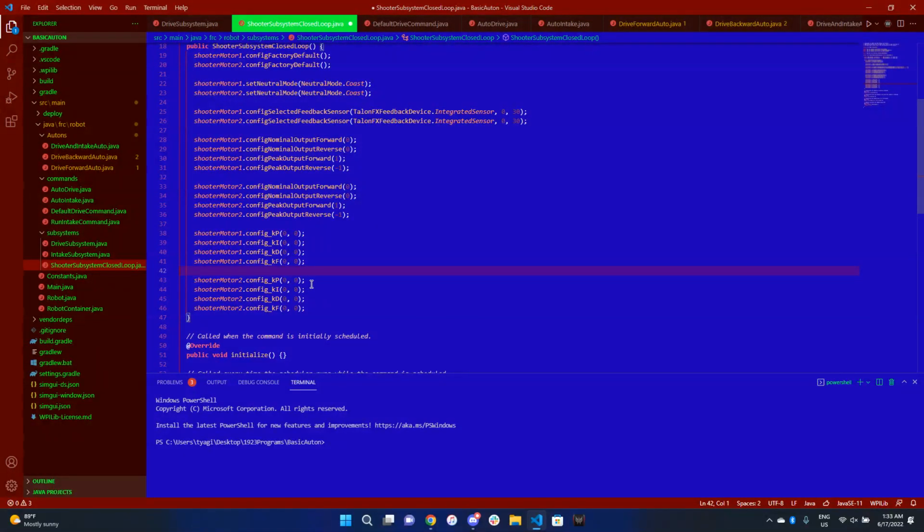And I'll give you a hint, the answer is somewhere in between 0 and 0.5. So don't think anything crazy like that. Now what I'm going to do is in comments here, I'm going to give you the actual value for our shooter, but I don't want you to use these now. I want you to experiment yourself and see how you can actually do that. So the first thing we're going to want to do, however, is actually give us an RPM so you can actually viably test this. So you can change your P and see the actual change in RPM depending on how you're commanding it.